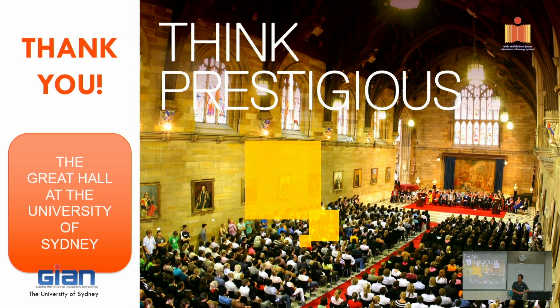So we're getting there. We get a couple of papers, we get some model. You remember here, like the channel section, I'm just drawing the web, and you're pushing the load in here, and it buckles, but it buckles and it can yield. And then the yield area is like this one. It's folding, but that's one. All right. And now, how do we work it out? How do we calculate the yielding Py in this case? That is challenging. So we need to come up with some simple model to do it, and that's where we are.